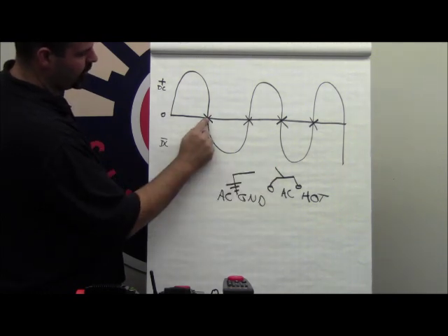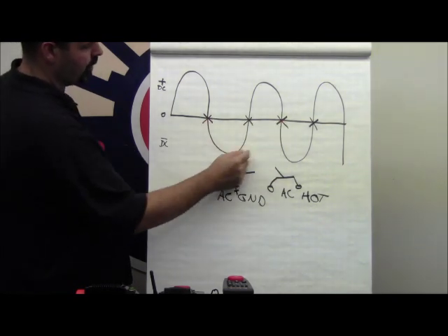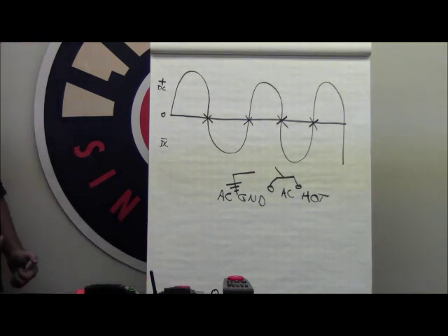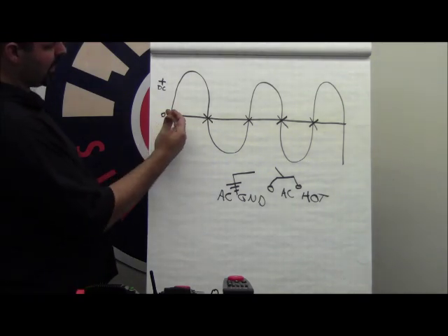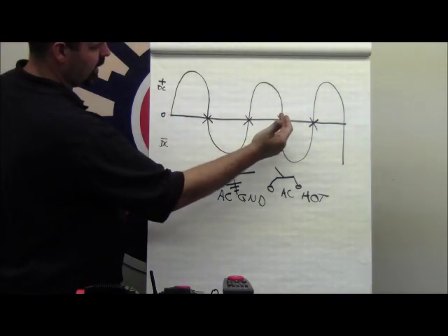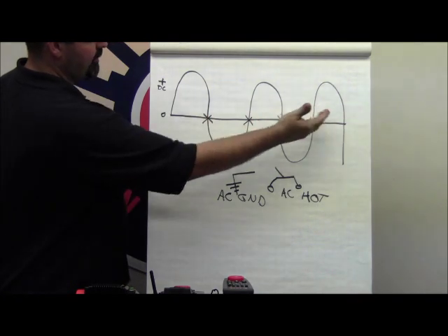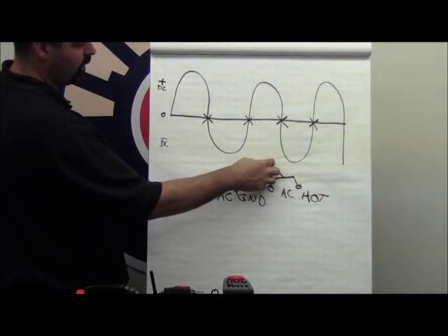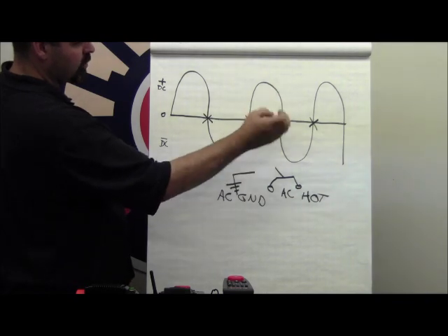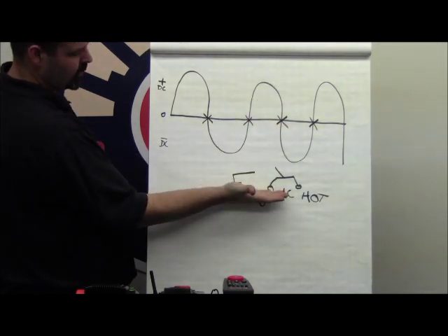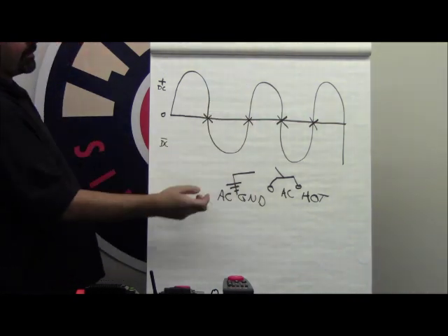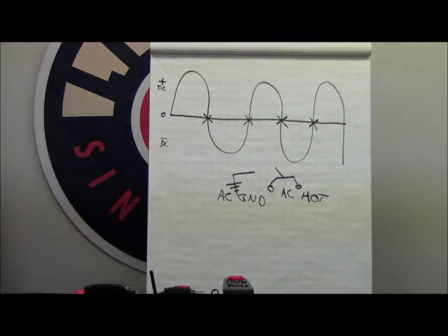So it too is looking at this sync pulse, because your transformers and your command base are all getting power from the electricity coming out of the wall. So as the command base sends a burst of signal 60 times a second, the receiver inside your locomotive, through its antenna, is synchronizing itself with the transmission of this signal and grabbing that signal 60 times a second.